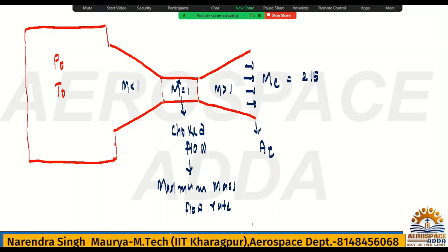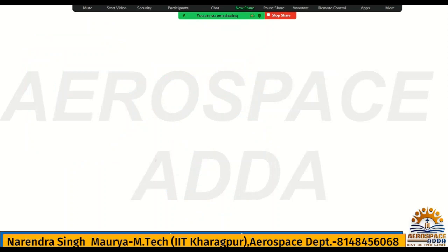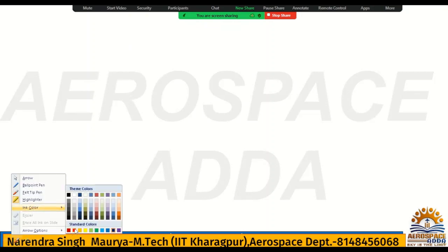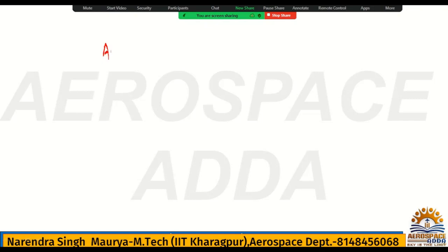How can you calculate it? It's very simple. Because you have the value of the exit Mach number, with the help of this you can calculate. How? Simple, the area velocity rule. Sorry, the area Mach number rule or area Mach number relation, you know very well. So the area Mach relation.